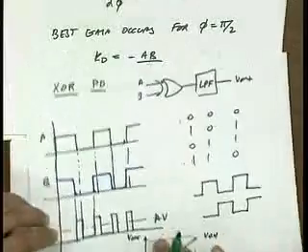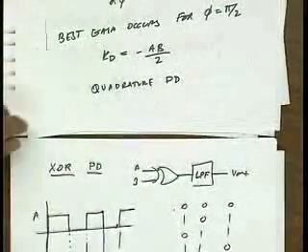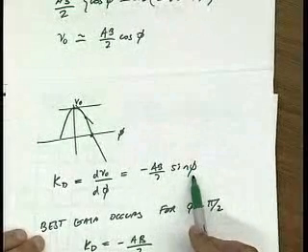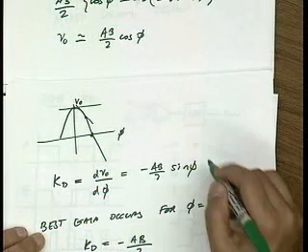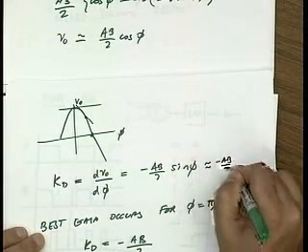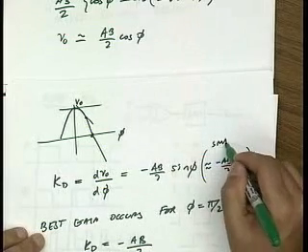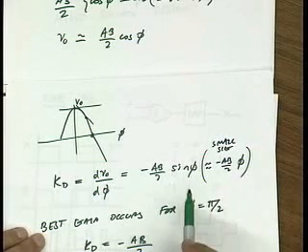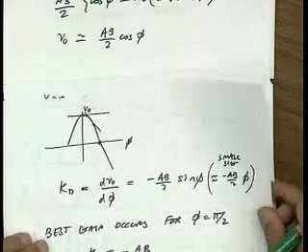In some applications, you do. But for the application that we're talking about, frequency synthesis, because our reference is at low frequency, you don't need to. Because remember, if you look here, there's a built-in nonlinearity in this phase detector, because this is sine of the phase difference. So sine is approximately phi, if phi is very small. Right? But from a large signal perspective, so this is from a small signal. But from a large signal perspective, there is this sine, and it does also change signs, right? Slope is sometimes positive, sometimes it's negative.